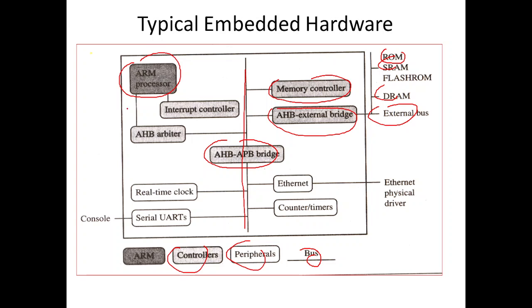It is connected via the AHB arbiter, and this whole unit is controlling sensors, or inside there are blocks which are available. When we program these blocks by using specific types of registers, then we are using these types of controllers, these types of features. So when I want ethernet, I am using specific types of registers, and those registers are available in the data sheet. According to the requirement we can program. This is the typical hardware which we use in embedded systems.